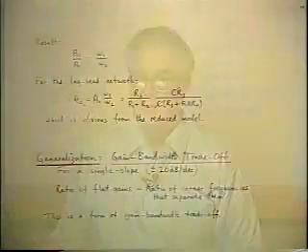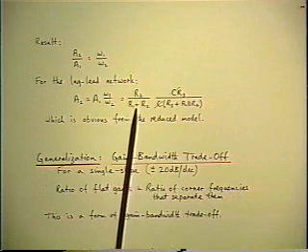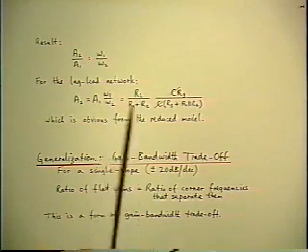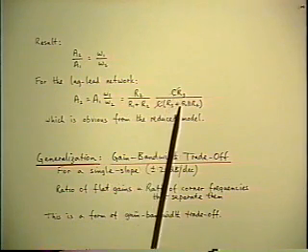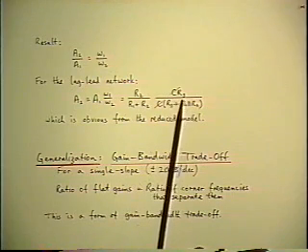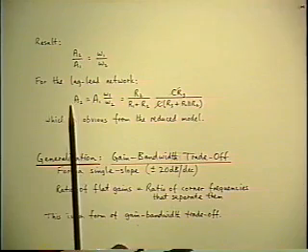In this particular case, it's easy to check that that ratio expression is correct, because A1 is the original resistive divider, and if you substitute for the definitions of the two corner frequencies, you get this ratio, the capacitors cancel, and what you're left with is the product of two ratios, representing now the infinite frequency gain.